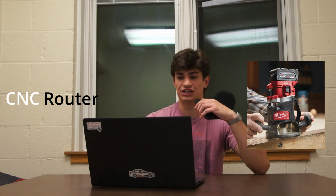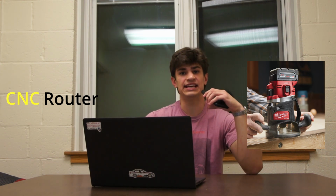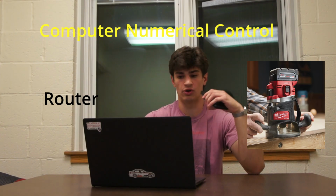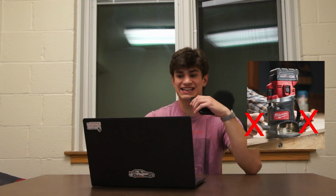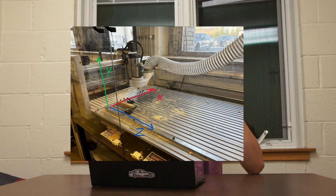What's a CNC router though? A CNC router is a router, a tool that uses a spinning bit to cut shapes, usually in the edges of wood. But the key word is CNC, or computer numerical control. This means we replace those pesky, imprecise hands with motors and tracks to move the bit along the X, Y, and Z axes. We have 3 axes, so we need a 3D path for the tool to follow, also known as a tool path. And a DWG file isn't that, so we have to use another program, VCarve.